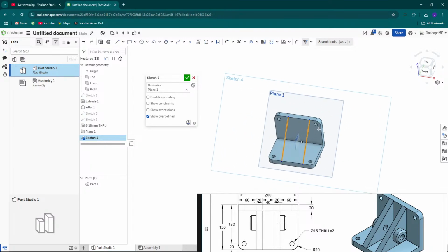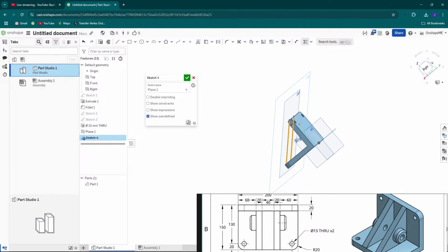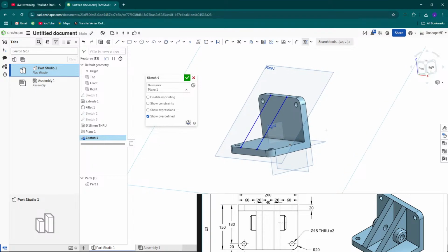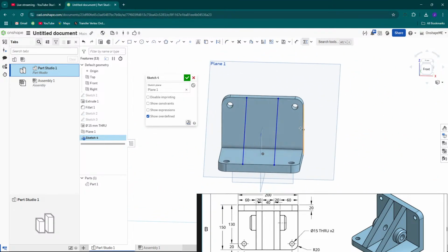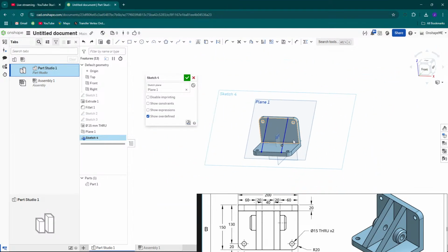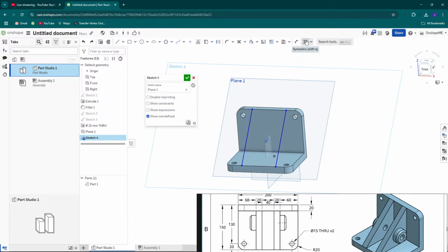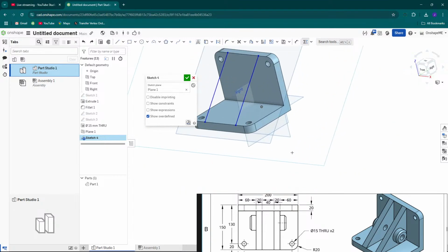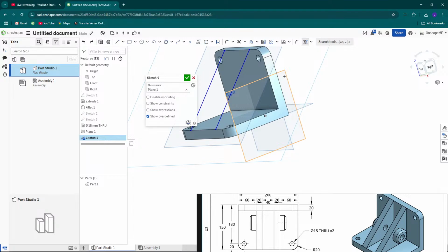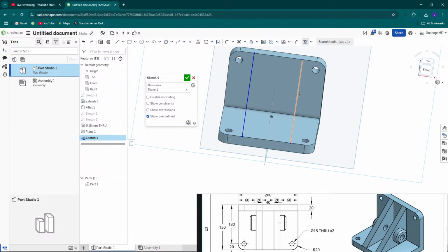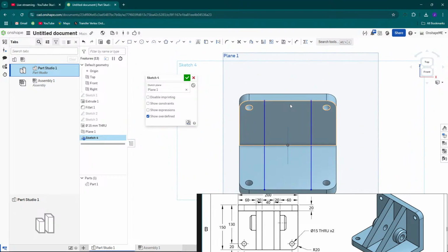Oh no, it did not. I think I didn't. Oh, here it is. We can choose the right plane lastly. Okay. Let's repeat. For example, we need to add symmetry constraint. We can click the symmetric button. Here it is already clicked. After that we can choose the right plane and these two lines. Okay, it is now symmetrical. Okay, they are moving in opposite direction.